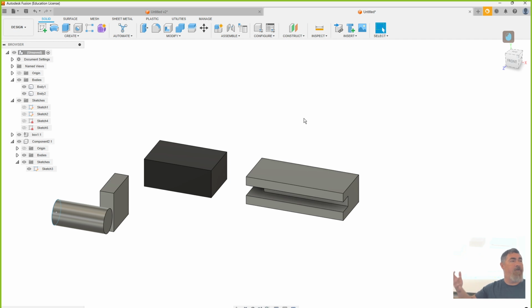So on any of your models, if you're doing it, you see the dimensions on the drawing. Think about, is this thing symmetric? Where does my origin need to be? How might I need to mirror? What patterns might I need to use? What constraints do I want to use? And what things can I preset as parameters that'll make it easy to change? What are things that might change, that are the most likely to change on this part?